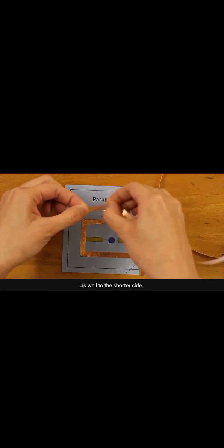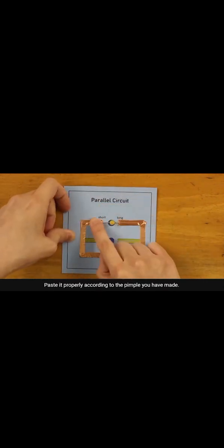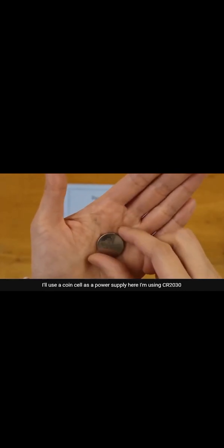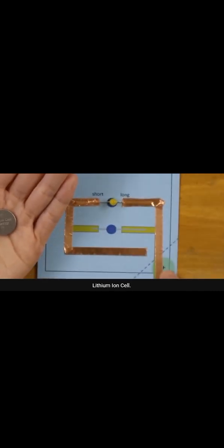So I will try to connect it on the left hand side as well to the shorter side. Make sure there is no air gap. Paste it properly according to the template you have made. I'll use a coin cell as a power supply. Here I'm using a CR2032 lithium ion cell.